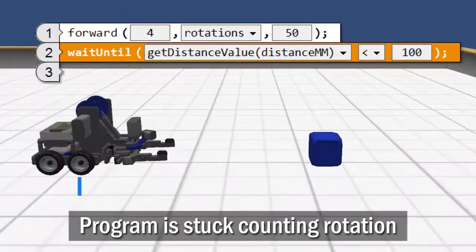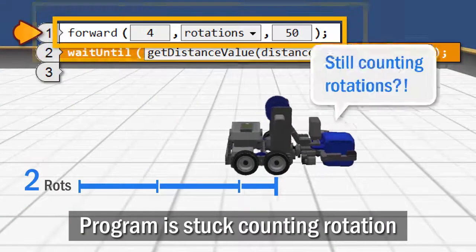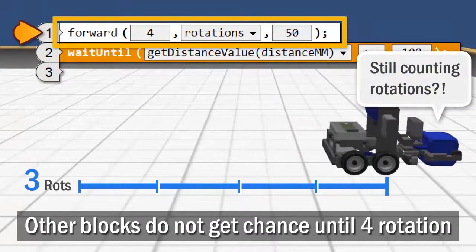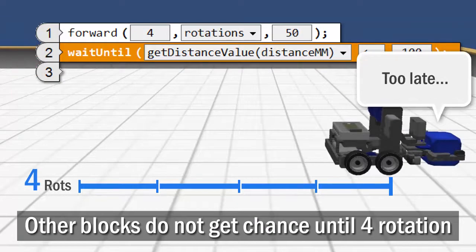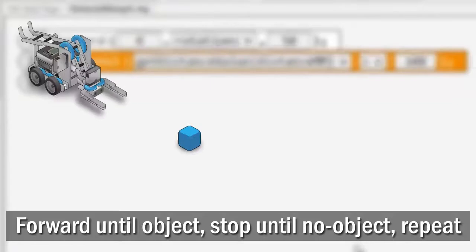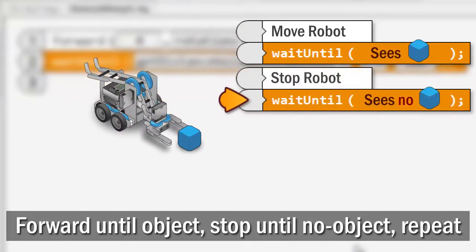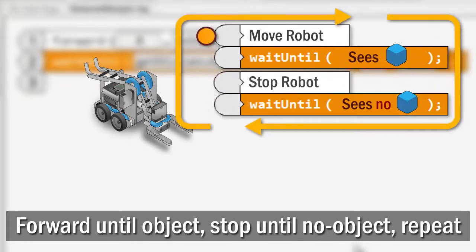The big 4 rotation forward command block doesn't work because it keeps control of the program too long, preventing any other blocks from getting a chance to do anything. So let's try a different approach. Let's have the robot move forward until it sees an object, then stop until it sees no object, and repeat that over and over.